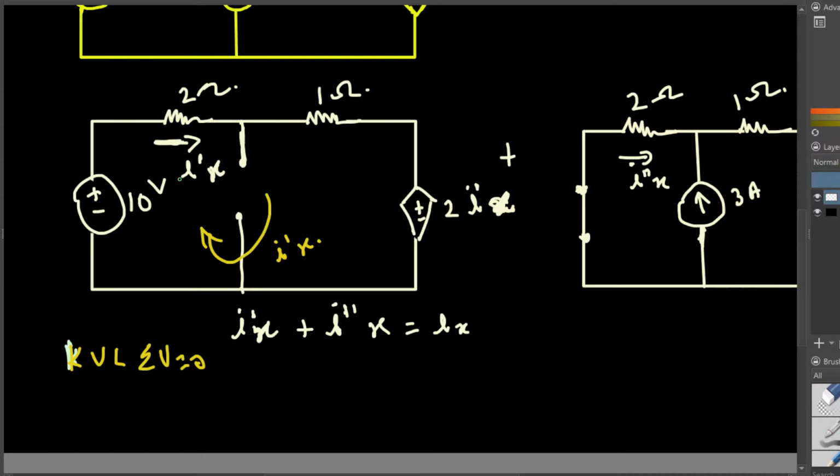So it's better to use this side, because if you choose the opposite side, you have to put a minus for it, and we don't want that. So if I choose this side, going from minus to plus, that's going to be minus 10V. And then here I can apply Ohm's law and write the voltage expression. V is equal to I times R.